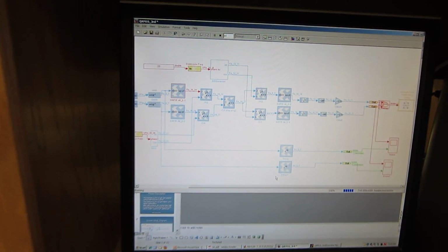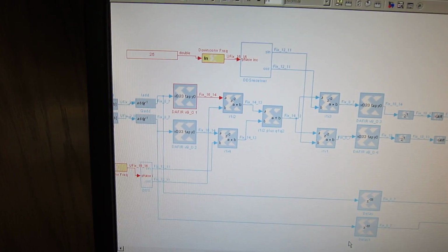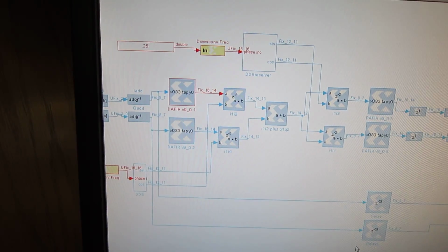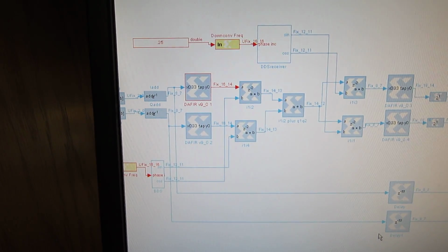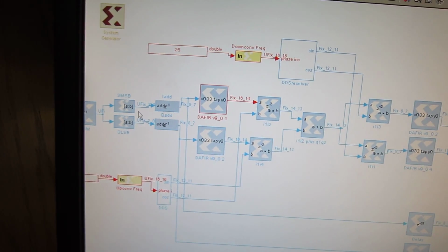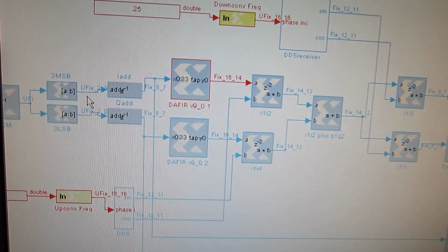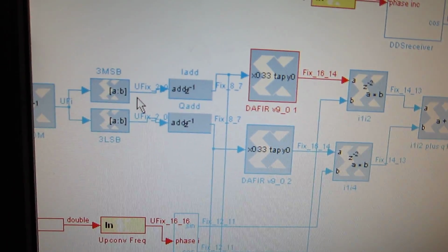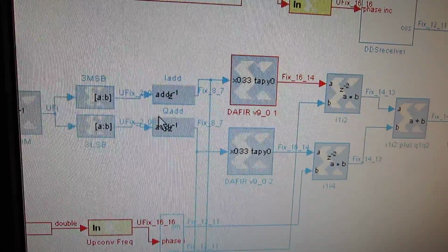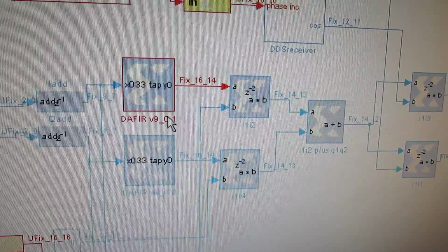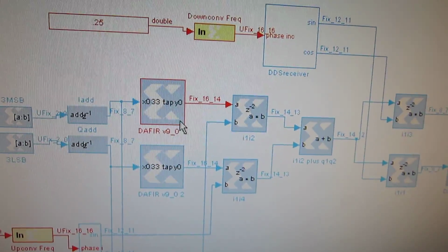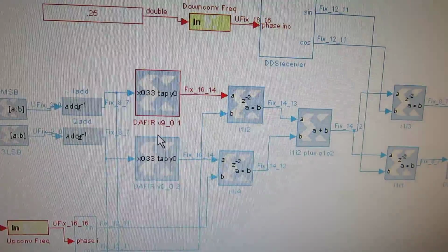This is our Simulink model. As you can see on the left, we have a random symbol generator, which uses MATLAB to generate random 4-bit symbols. We then split them into the in-phase and quadrature components, which we then map to four levels. We then pass that through a square root raised cosine filter for pulse shaping. This is to both reduce the bandwidth and minimize the intersymbol interference.